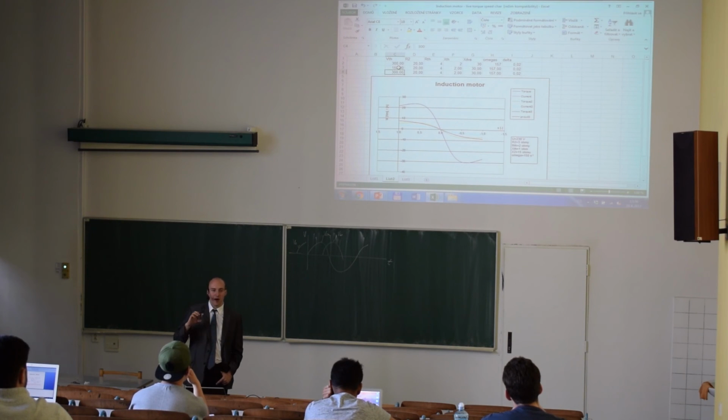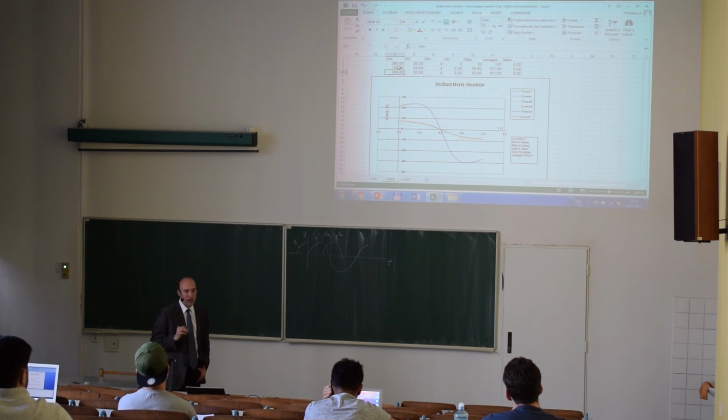So if I power that with 150 volts, I am expecting that the torque produced by the motor will be about 1/4 of the 300 volts motor. So you can change also the speed of the motor by changing the power supply voltage, but you are using the slip as an intermediate for that.